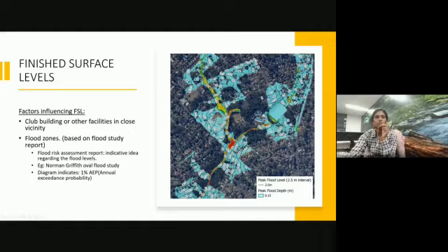This is showing all of this red area is where the maximum amount of water is flowing, and this is actually a creek. This red area is the creek where all of the water from this area gets drained away and outside. Okay, so can you see this level here? This level says 72.5. What it means is that was the reduced level up until which the peak flood levels reached.